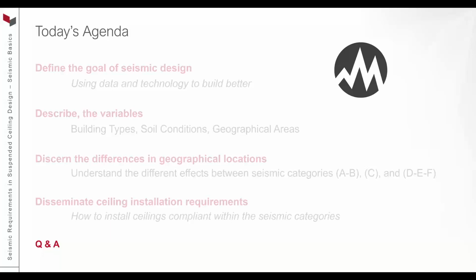So we don't worry about regular edge tile. We can cut it in or not cut it in. It can be tightly fit if it's a full module on the perimeters. It doesn't impact the seismic requirements. So we build the grid according to the ASTM E580, and then insert the tile accordingly to make sure that it looks good in the end result. So the tile, we don't have to worry about tile, but when we get into metals and woods, then we have some different scenarios that we look at when it comes to DSA regulations and OSHPD regulations, or schools and hospitals governances.